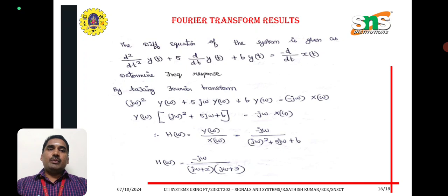The differential equation of the system is given as d square by dt square of y(t) plus 5 into d by dt of y(t) plus 6 into y(t), which is equal to minus d by dt of x(t). Determine the frequency response. d by dt can be replaced by jω, so we get (jω) square into Y(ω) plus 5 into jω into Y(ω) plus 6 into Y(ω), which is equal to minus jω into X(ω).